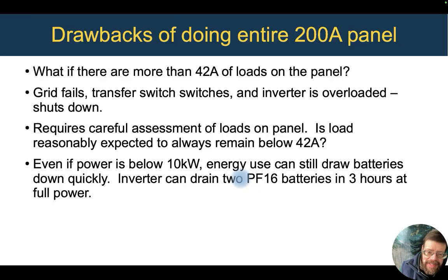A second issue is, even if we stay below 10 kilowatts, 42 amps, that's still a lot of energy use. If we're pulling 10 kilowatts and we have two PowerFlow 16 batteries, that's 3 hours of backup power. Not very long.